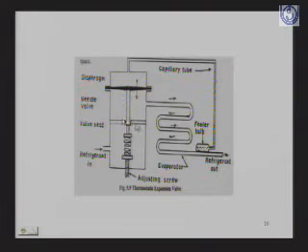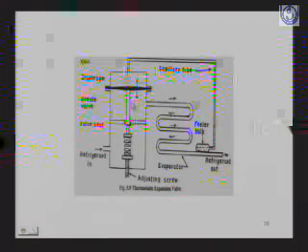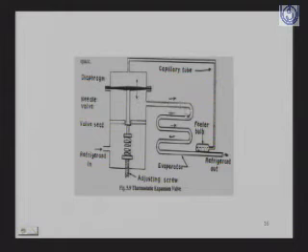Now the flow is controlled, whether we are allowing less refrigerant to go into this side, or more refrigerant. This depends upon this sensing bulb. This sensing bulb, through the capillary, controls the diaphragm. Now if the evaporation is more, then it will allow more refrigerant to flow inside.